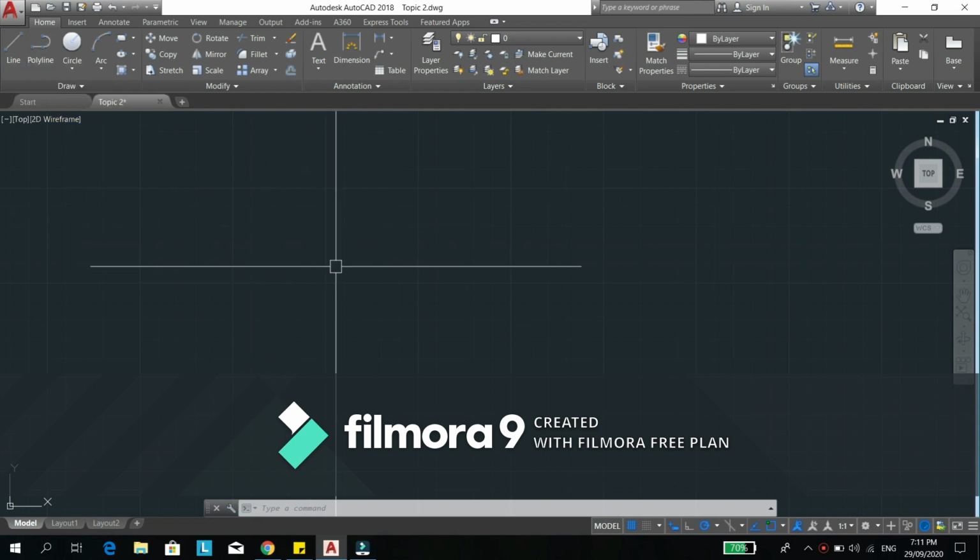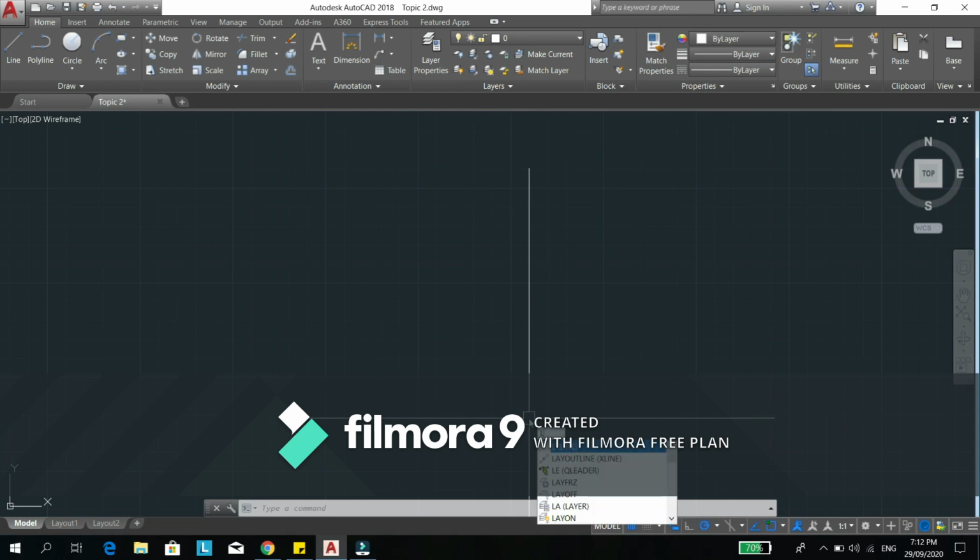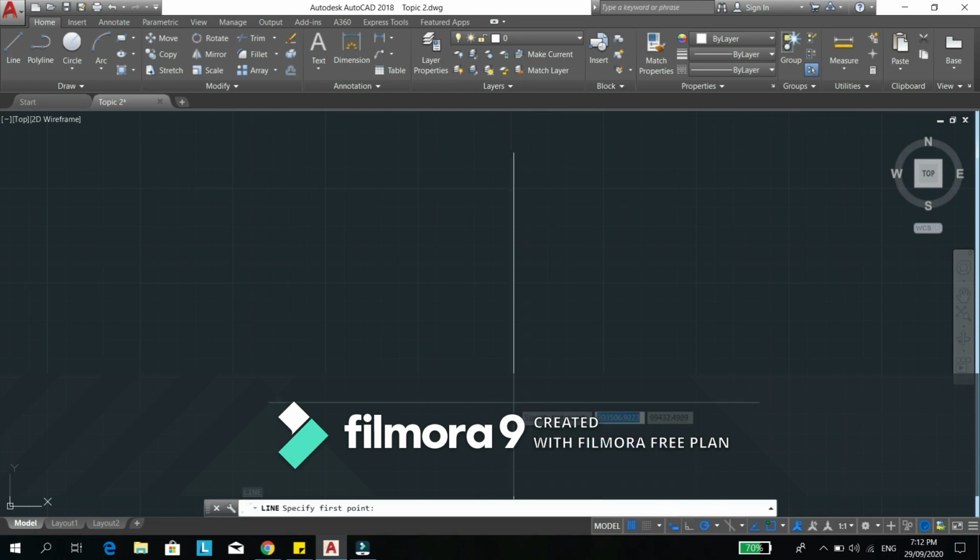So in line, in order for you to create a line, you have first to type L and press enter for shorter command, or just click this icon. So type L and press enter. Here you can see that it's for line. So enter.